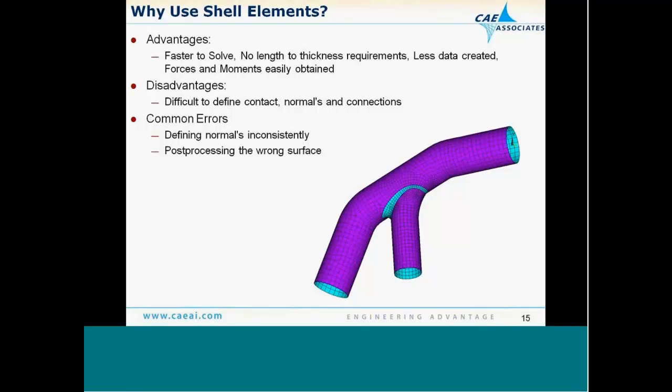One of the things you've got to be careful about with modeling shells is making sure you have consistent normals. So do I have consistent normals such that when I put a pressure load, the pressure will act consistently over all faces? Mechanical APDL, for example, when you plot your model with the element types active, will show the inner and outer surfaces with different colors. So you can clearly indicate the region where I need to reverse my normals to get consistent results from the loading perspective, and it also helps in the post-processing.